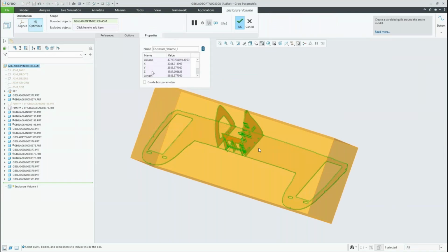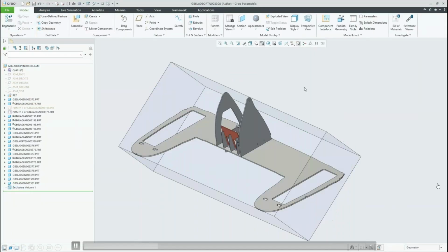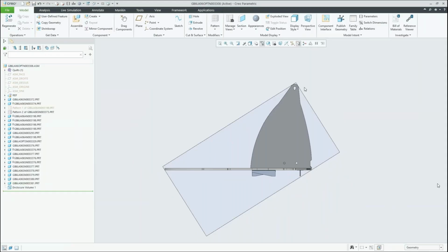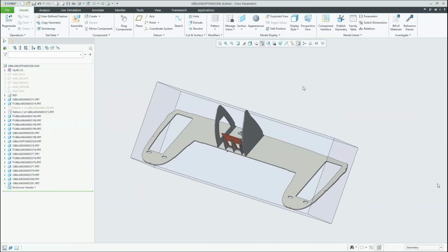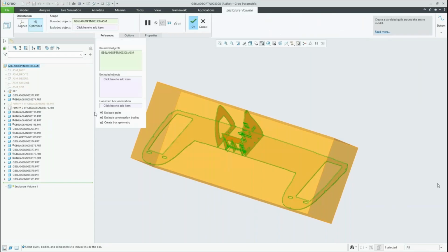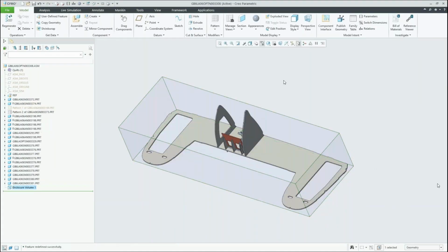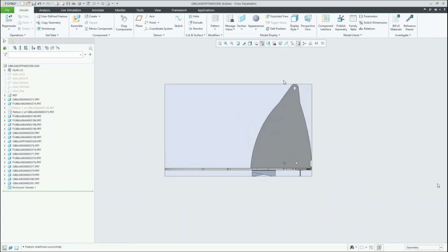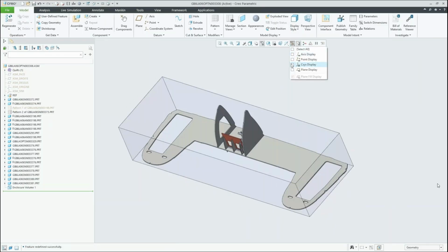Yeah. So you have an aligned, and an optimized. Optimized is the smallest possible shape with the part that we have. And aligned is aligned to a coordinate system or to a surface. The box orientation you can change depending on a surface, like shown here. So that's also sometimes what you want, because you want to put it into a box or into a container like that.